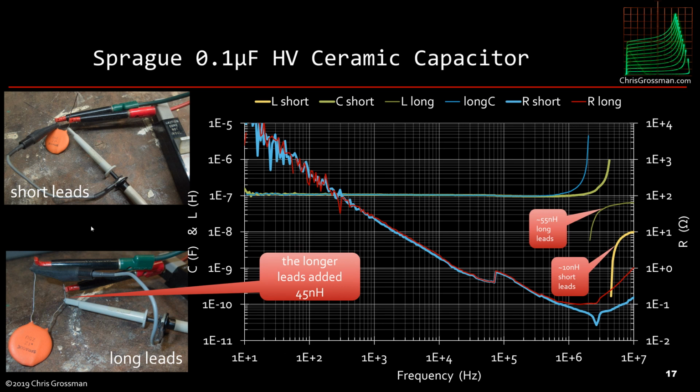So the impedance is in magnitude and phase. You can then calculate the real part and the imaginary part of that. The real part is the equivalent series resistance, and then the imaginary part is the reactance. If the reactance is positive, that means it's inductance. If the reactance is negative, it's capacitance. And so we can take those calculated values and plot those out.